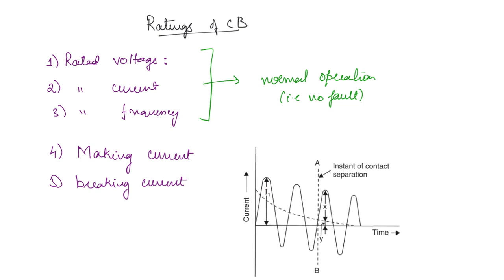Now we have already discussed the circuit breaker doesn't right away break the contacts, right? It will wait some time. After that only it is going to break the contact. So now you can see at the very instant of the short circuit, the instantaneous current is going to be very high and it is going to reduce over time. The fault current itself is high, but at the instant of fault occurrence, it is going to be even higher.